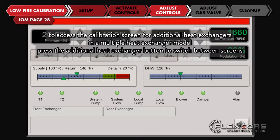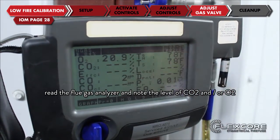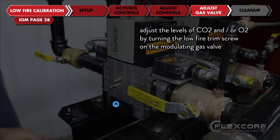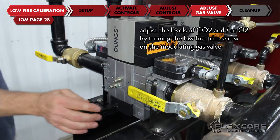To access the calibration screen for additional heat exchangers in a multiple heat exchanger model, press the additional heat exchanger button to switch between screens. Read the flue gas analyzer and note the levels of CO2 and/or O2. Adjust the levels of CO2 and/or O2 by turning the low fire screw on the modulating gas valve.